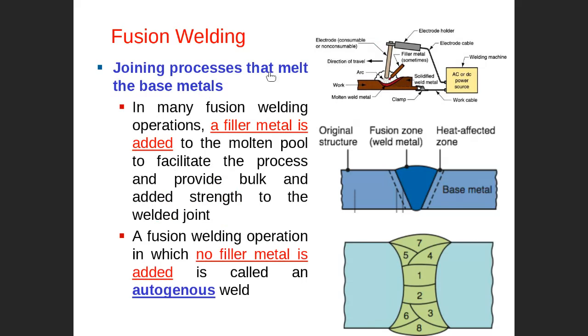We discussed last time about fusion welding and said that in fusion welding we melt the two substrates. I mean, in a welding zone, definitely in a welding zone, we melt the two substrates. In fusion welding, or liquid state welding, we melt the parent material in a welding zone. And this one, I remind you, is limited to welding similar material. Please remember that all the time. This is limited to welding similar material, and in fusion welding we usually use a filler material.